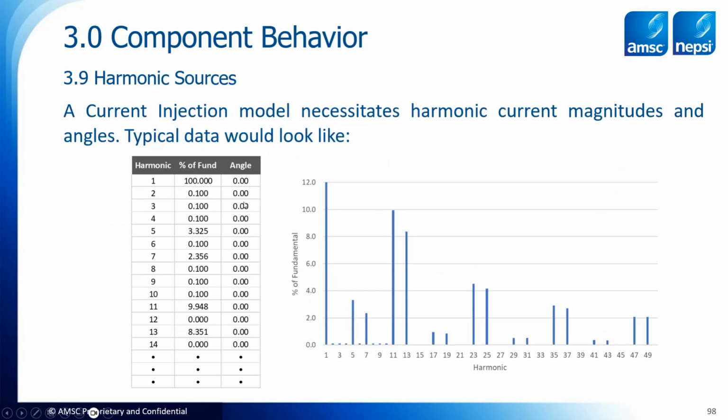That would typically only be done when I'm looking at multi-pulse rectification systems, and I want to simulate the cancellation of certain harmonics, like for a 36 or 48 pulse system. I have a plot over here of these numbers. And obviously we can tell, since the 5th and 7th are fairly low, that for this example set of data, it's predominantly a 12 pulse rectification system with some amount of residual harmonic distortion at the harmonics that are being canceled.